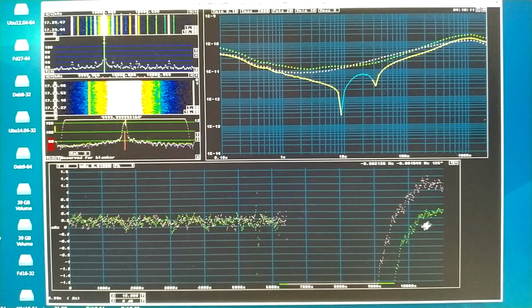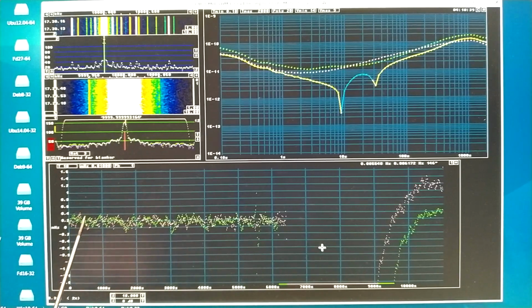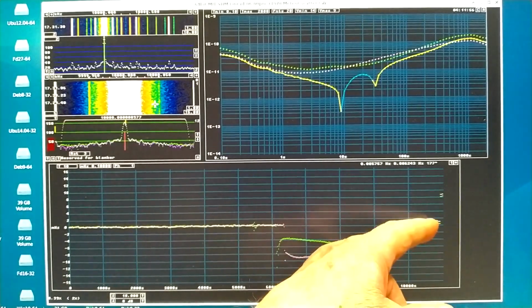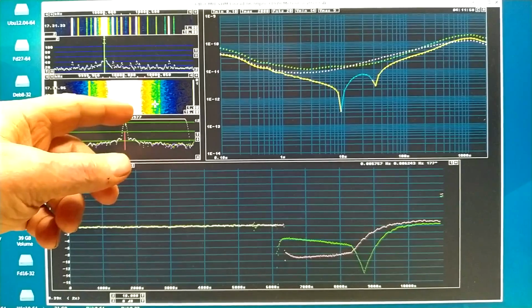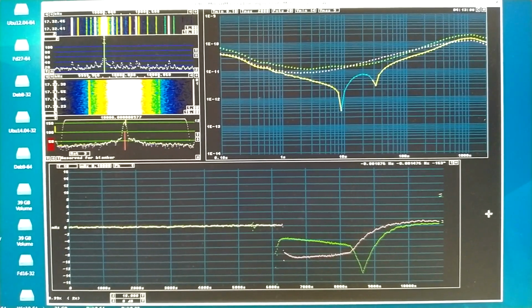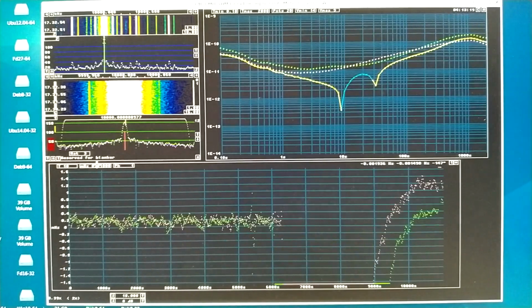And it seems channel 1 is less noisy than channel 2. But before, when I look here, it seems channel 1 is more noisy than channel 2. It seems I changed the frequency by clicking in this box somehow. I've tried to restore the original. I will change now the vertical scale to see better what happens here. So, 10 times more gain.